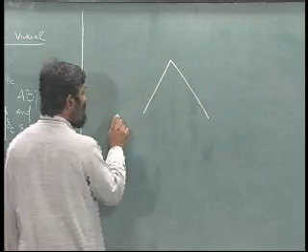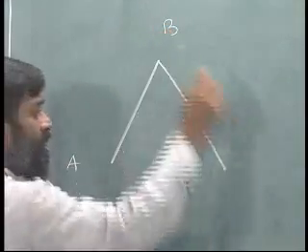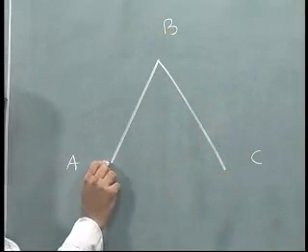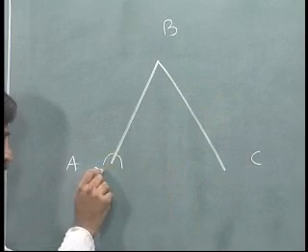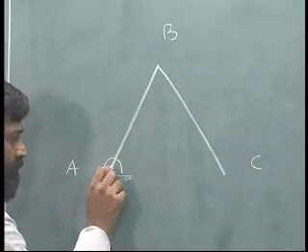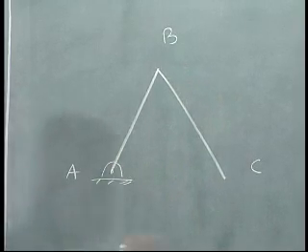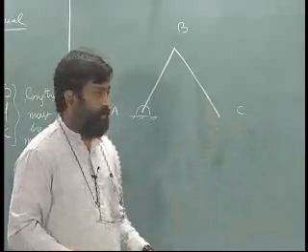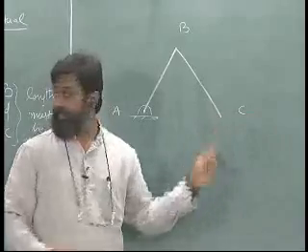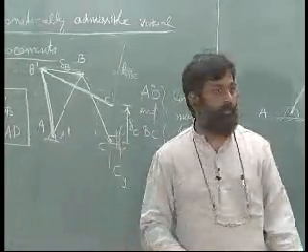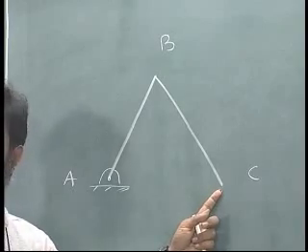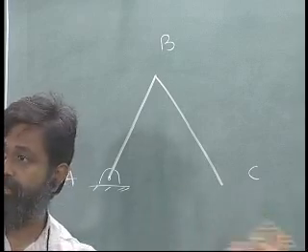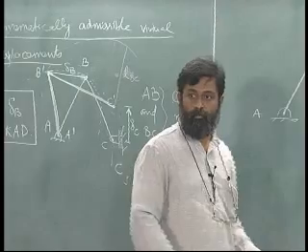So, I have this is A, B and C. Let me retain this hinge support here. Let us say I want to find out the horizontal reaction now. So, what would I do? This is a pinned support. I would want to release the horizontal displacement and apply a force.